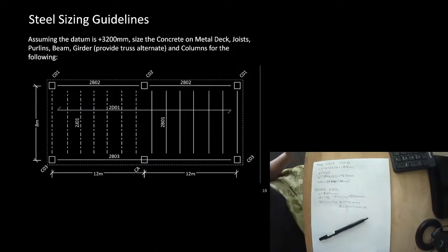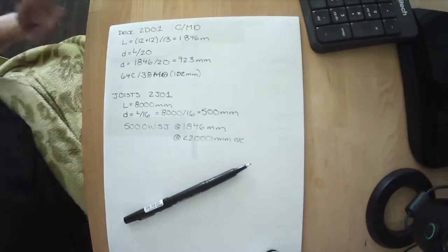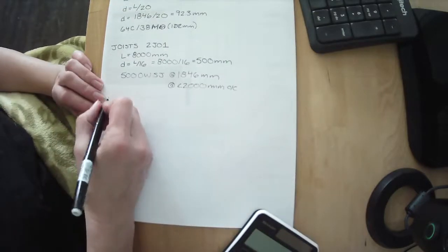Okay, the next thing is the purlins. So the purlins look like they were the thing that's doing the exact same job as the open web steel joists are right here. So these members were all open web steel joists, and we can tell by this funny dashed line. And then these ones are all our 2B01. We know a purlin is just a beam. It's just a beam that in context isn't working that hard. It doesn't have the big, heavy job.